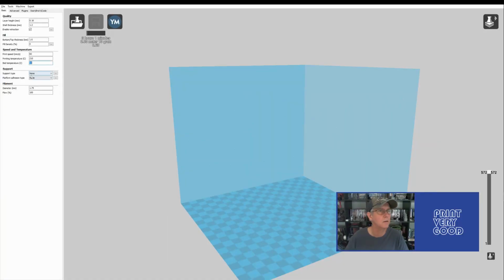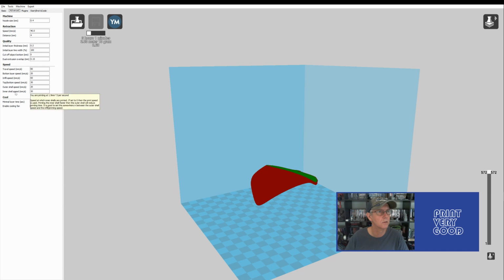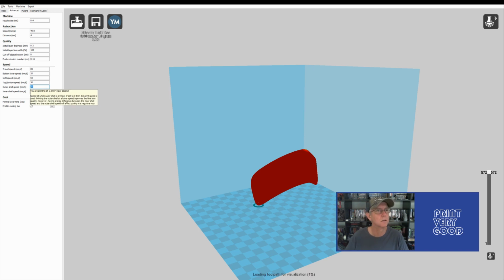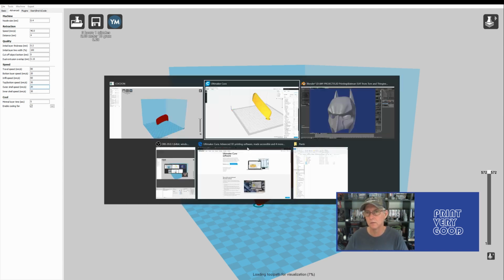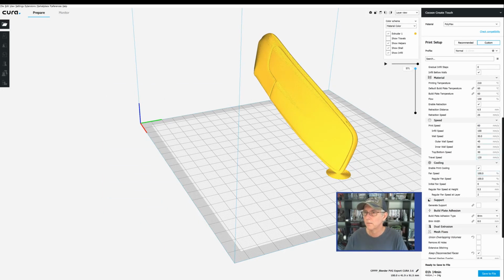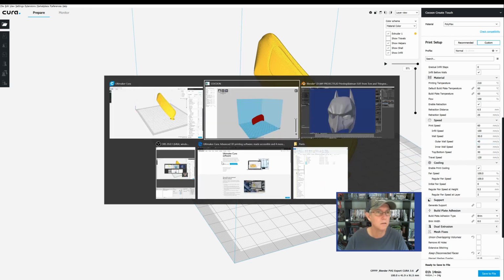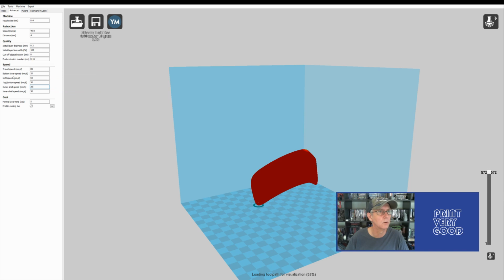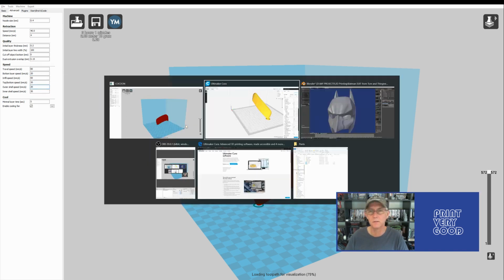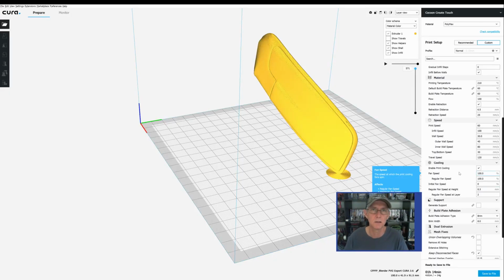Wall speed 30. Travel, infill, outer speed 20. So okay, it's a slower outer skin, so for a better quality print. We're going 30 here. Oh, 40. Outer wall speed 40. Inner wall speed 80. And I've got outer wall is 20, inner's 30, so that's a big difference. Okay, that's where the speed differences are coming from.